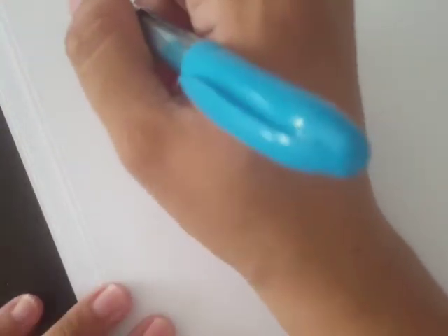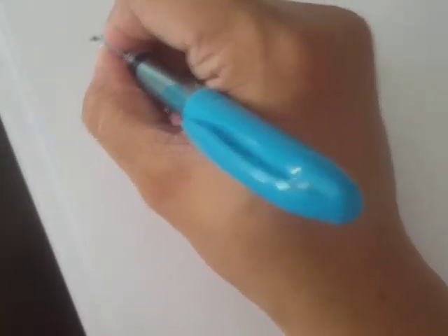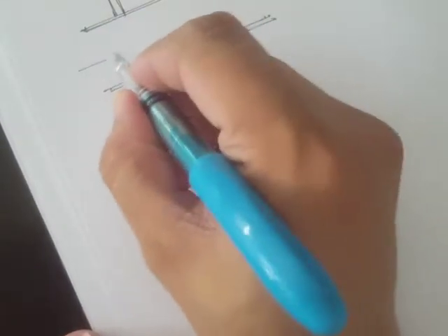All right, another application is the measurement of flow using the piezometer and then the pitot tube meters. So for example, we have this pipe right here, a horizontal pipe, and if we want to measure the static pressure, then we can just tap a piezometer right here.